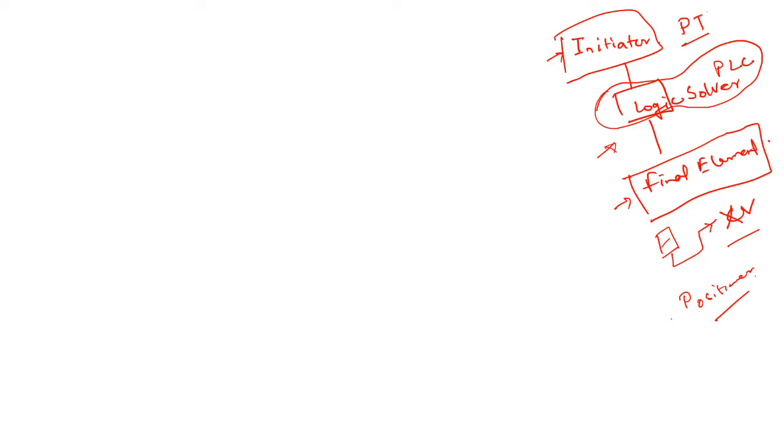So when we say logic solver, again there is a PLC, and the PLC is connected to an engineering workstation. The engineering workstation is basically used to configure and make the logic, and the PLC is connected to all the IOs, input and output, which are the pressure transmitters, all the valves, everything, right?